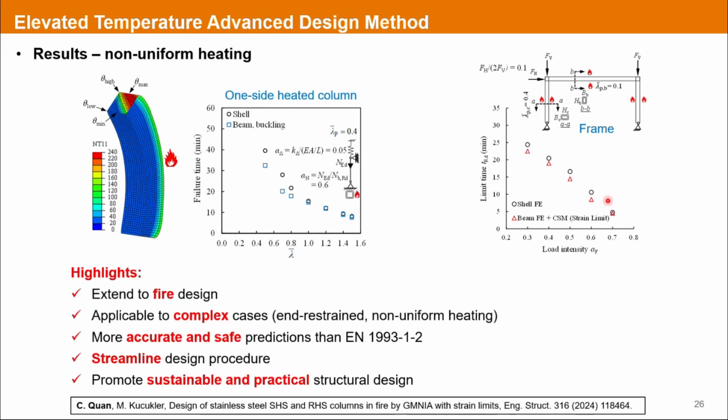As a conclusion, our study extended the advanced design method to fire scenarios, making it applicable to more complex cases like unrestrained members and non-uniform heating cases. Compared with the hand calculation approach given in Eurocode, the elevated temperature advanced design method could generally provide more accurate and safe predictions.